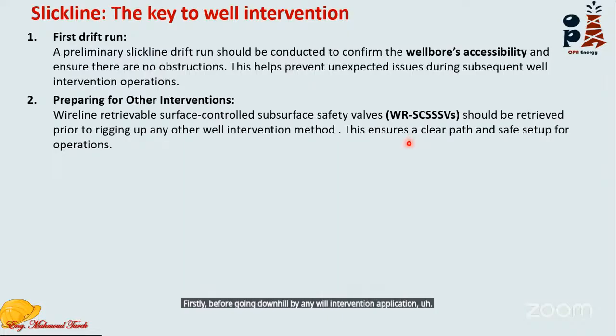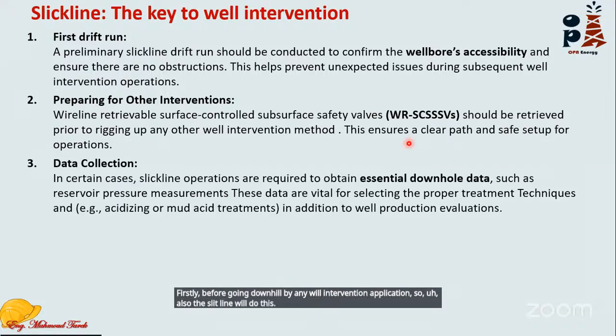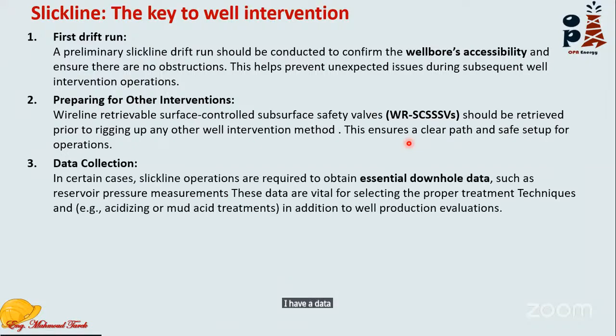So also the slickline will do the data collection, recording pressure and temperature and so on for any upcoming application like water shutoff or reperforating. You need to collect those data by using the slickline.